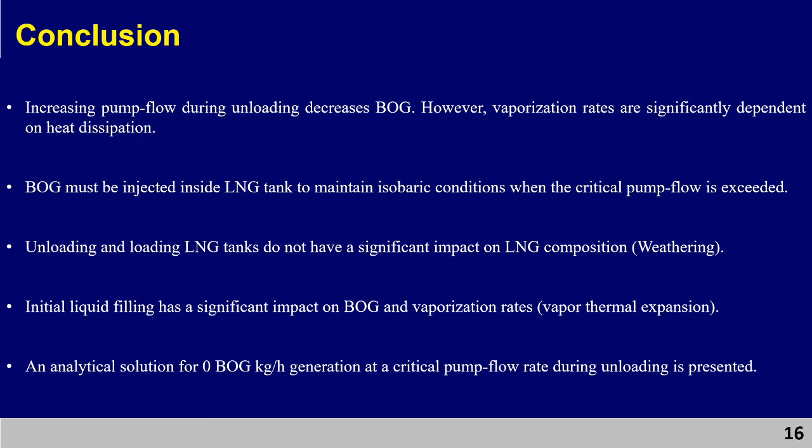However, the vaporization rates are significantly dependent on heat dissipation. BOG needs to be injected into the tank to maintain isobaric conditions when the critical pump flow is exceeded. Unloading and loading do not have a significant impact on LNG composition. The initial liquid filling has a significant impact on BOG and vaporization rates, and vapor thermal expansion has a role to play, and this will be investigated in future research.